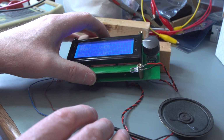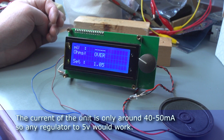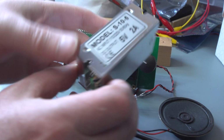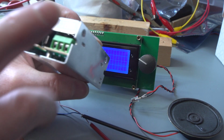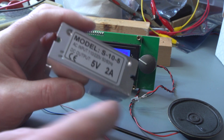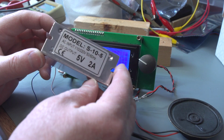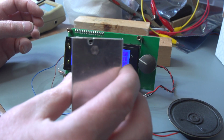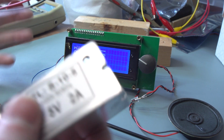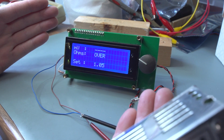Now, power supply wise, we haven't talked about that. You could run this off a 9-volt battery and maybe put it through some sort of DC-DC converter to get it down to 5 volts. Another way of doing it is to use something very small, like a little 5-volt switch mode power supply. This operates from the mains in, 5 volts out. This is a 2 amp device. It's far more than we really need. We could easily power it by something like that. It wouldn't even warm up. And then you could plug the thing straight into the mains, put it in a proper project box for a bench, in a bench type case.